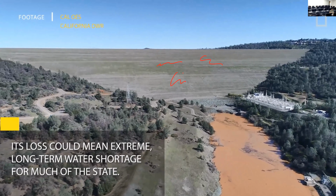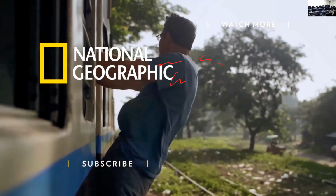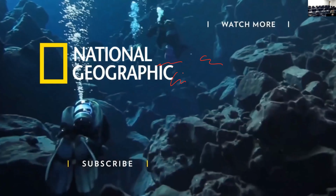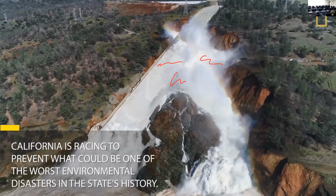And the interesting problem was that if they lose the emergency spillway, they lose the powerhouse which operates the gates of the main spillway. So they had to be very careful opening the gates of the main spillway in such a way that it doesn't damage the downstream hydropower plant. Because if the power plant is out of the equation, then you cannot open or close the gates. It was a really interesting problem back then.